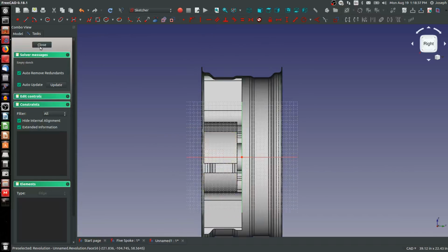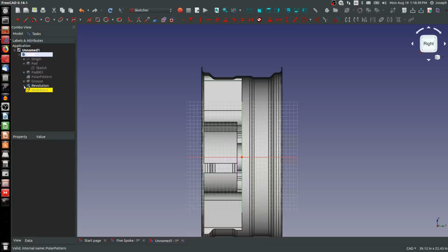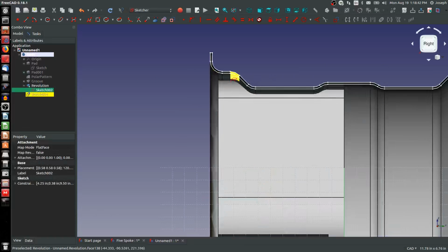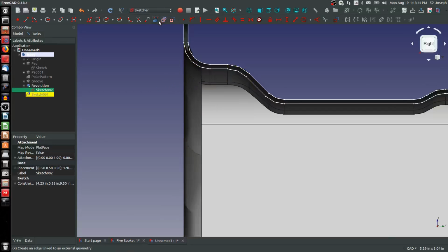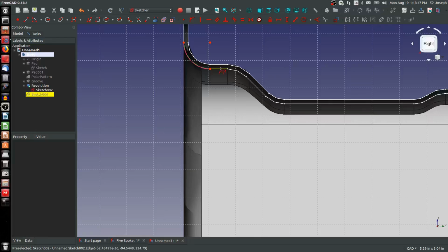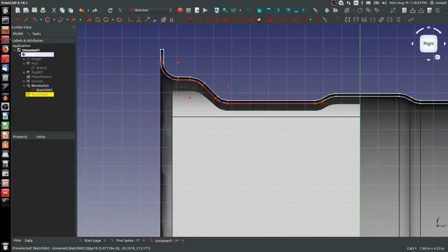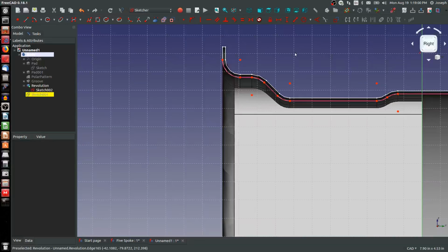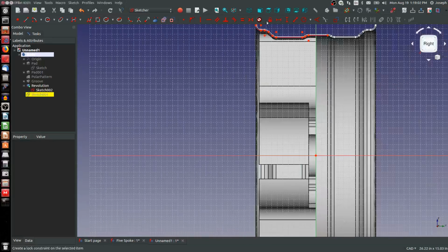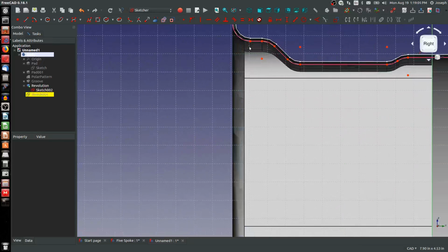All right, first thing, let's go to the sketches. You can use the space bar to show the profile that I've sketched along. I can import from that sketch the edges that matter to me. And this will be a large guide in the shaping of these spokes. I don't think I'm going to use all these imported edges at the same time, but I will use most or all of them eventually. What I'm going to do first is choose an arc and make it coincident onto this arc.